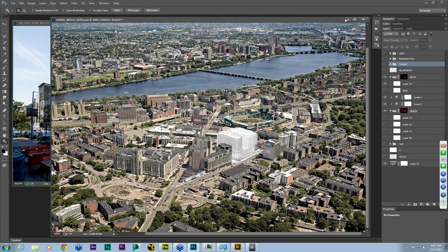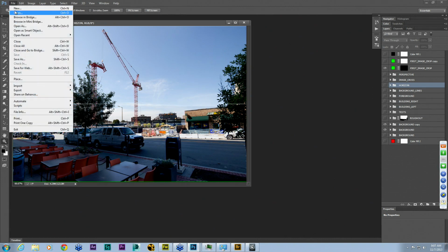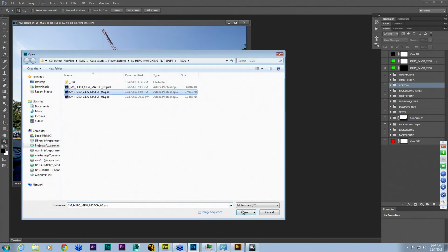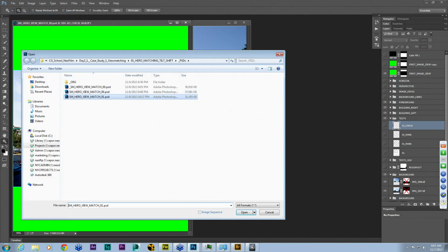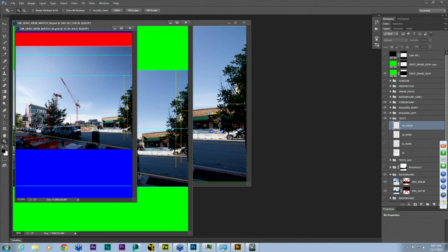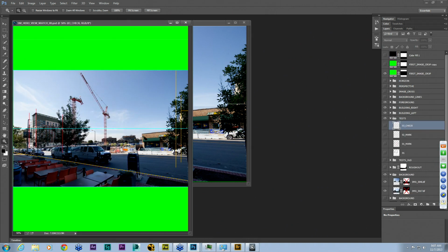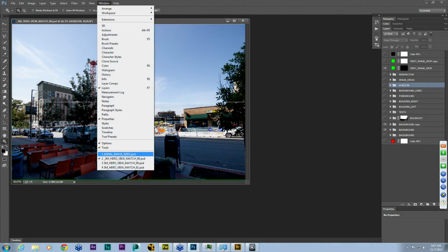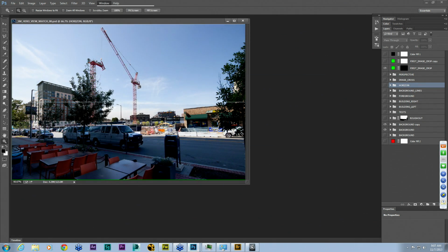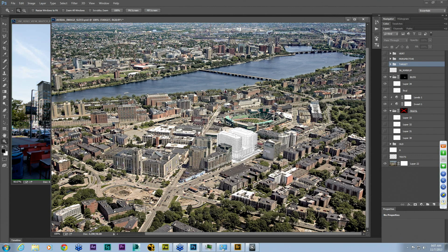Back when we had done it, the idea of GPS data being available didn't really exist. It's always been from the ground, and often we would use known surveyed things like manhole covers and telephone poles that were in the engineering information, and we would put the requisite geometry in.